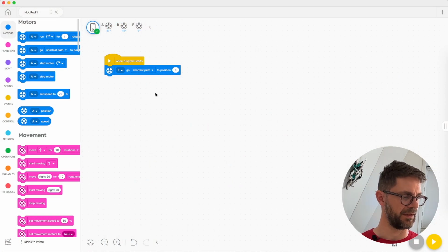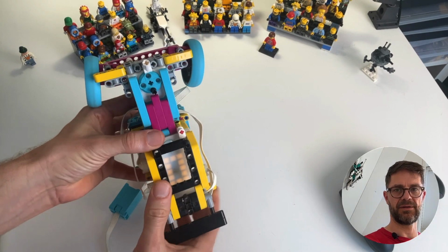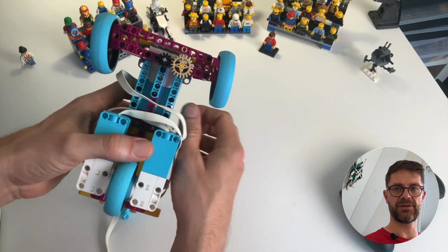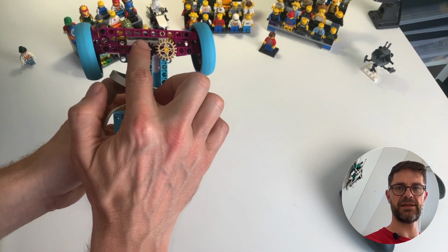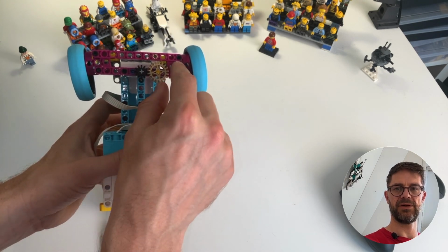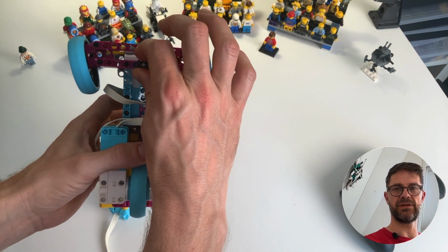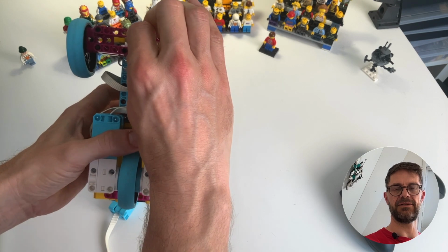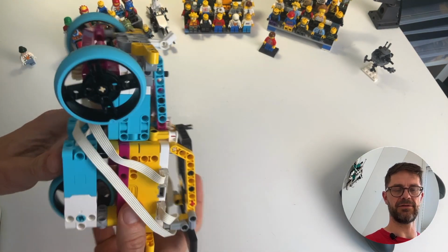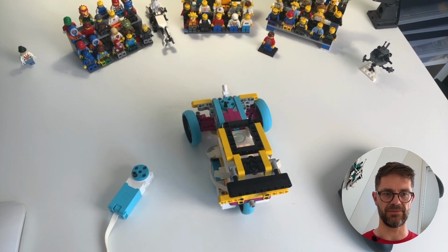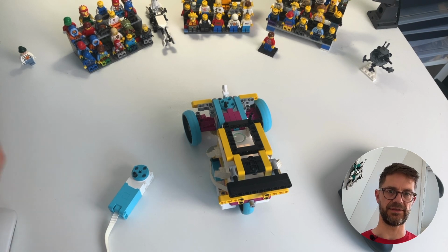Now, what you can see is that the motor is in the 0 position, all right, but the wheels aren't, and that's because there is some gearing involved. So the black gear here is straight, but because this one is straight, the tan gear here cannot be straight. So there's probably a 15-degree difference that we have to take into account. So let's see if we can make the motor come really to 0, or at least let's see if we can make the wheels center accurately.